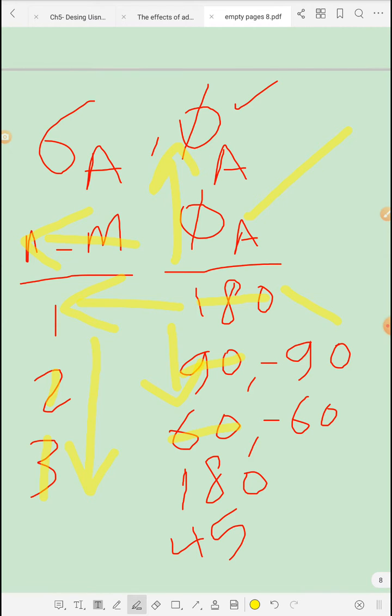So if we keep increasing the n minus m value, which is the number of asymptotes, this means that the root locus will be directed to the right hand side of the s-plane, toward the j omega axis with smaller angles, and it will be unstable using smaller values of k. This we have already previously covered, but just as a reminder.